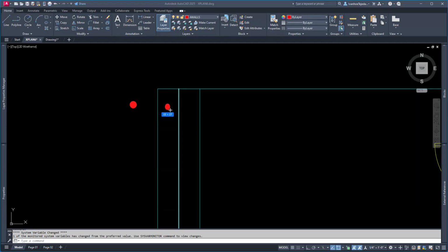And this is what we refer to as the tread of the stair. The line that you see here, that is the riser. So I've gone up 6 inches. And then I step here, and that's going up another 6 inches. So now I'm 12 inches off the ground. And then another 6 inches here puts me at 18. So that's 1 foot 6. So just imagine taking those steps up, up, up to get there.